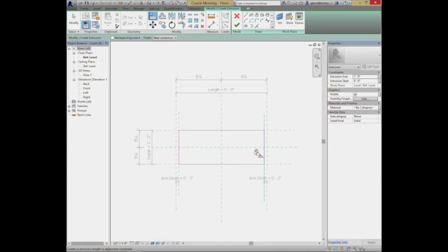Okay, so we did that. We need to go through and give our extrusion some sort of start and end, and we'll just put some manual value in here. We'll later figure out how to make that a parameter. Let us say it's going to be like 6 inches off the ground to 1 foot off the ground. That's pretty fine. We can give it a material here if we want to now too.